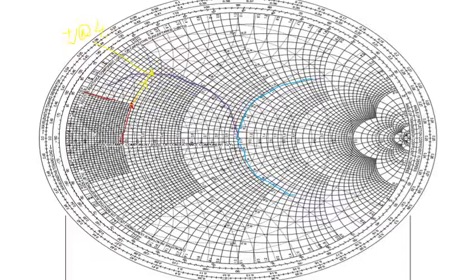Plus j 0.4. Am I clear? How did I find? You moved along the solid circle and you have intersected that dotted line. Since you moved along the solid circle, you have to find about the solid arc. Now that is the destination point. Now the question that comes is, what is your source? You started from ZL point and this ZL point is actually marked here. Can you all see this, everybody? I'm again highlighting it.